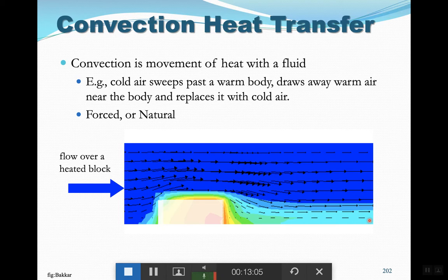But if it starts blowing for even less than a minute, you will start getting very cold, although you still have your jacket. The reason for that is, as soon as wind starts blowing, the transfer mode changes from conduction from the surface of your jacket to convection through the surface of your jacket. And as we said, convection and forced convection is a couple of orders of magnitude larger than conduction. That's why in winter you feel cold in that condition.